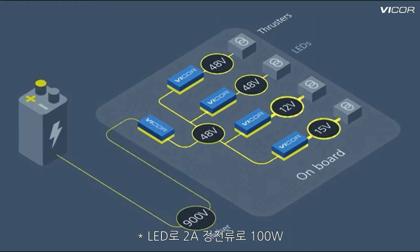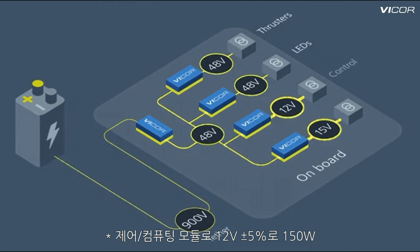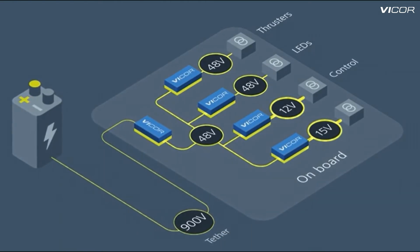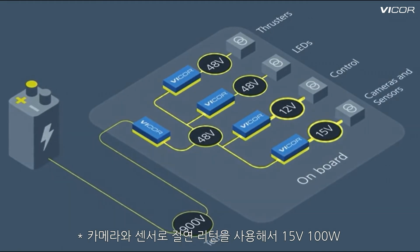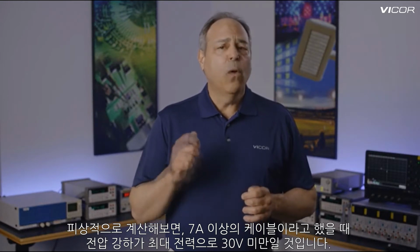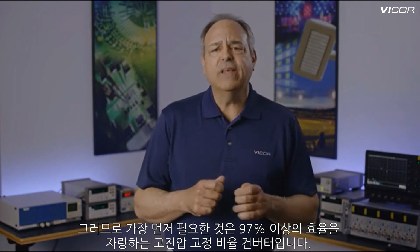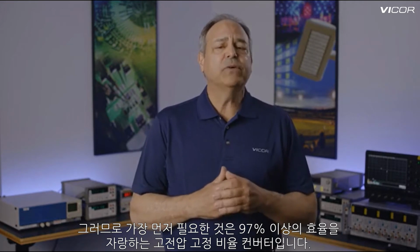100 watts of LEDs with 2 amps at constant current, control computing module with 12 volts plus or minus 5% at 150 watts, cameras and sensors with 15 volts, 100 watts each with an isolated return. A cursory calculation shows a tether with reasonable ampacity above 7 amps will have less than a 30-volt drop at full power.